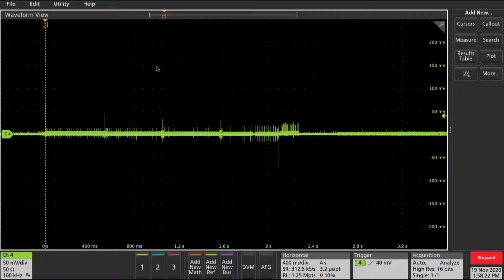So the first thing to notice here is we can see what appear to be different transition points in this sequence. There's some AC transition points or some different frequency jumps that occur off of our DC baseline, and we can see where those transition points occur. It doesn't really tell us at what DC offset the core voltage has scaled to, of course, but we can get a general sense of it. It's not really clear whether these large peaks indicate the greatest transition, or if these smaller peaks have anything to do with what's going on in this particular core rail. So the general synopsis is that with AC coupling for this particular rail, we're not really getting a good sense of what the complete picture is, and what the different offset jumps this particular core voltage is rising to.